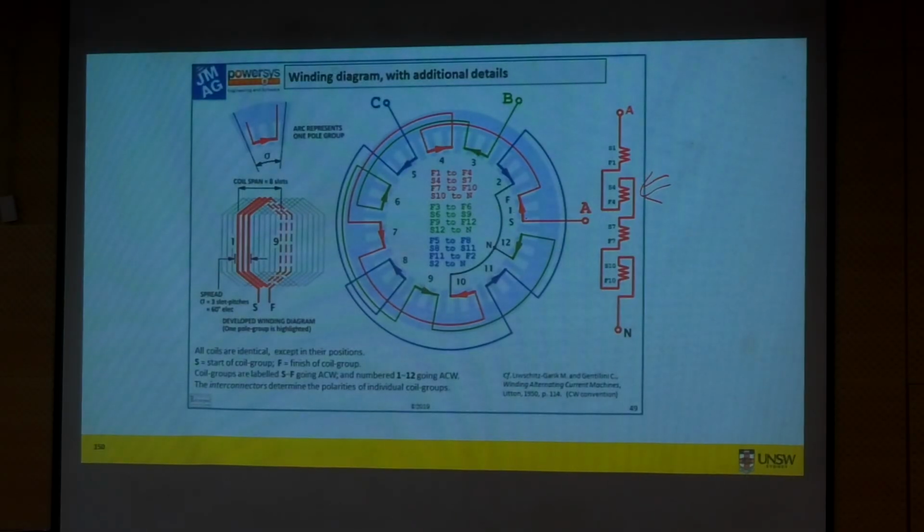So first coil is, in this machine, 3 slots per phase. Okay, so one phase requires 3 slots to distribute. So one coil is in these 3 slots here. The second coil is done in a different way, you can see. Okay, so there could be some implication for how they are connected. The second coil is connected as coil 1, and coil 4 is connected in a bit different way.